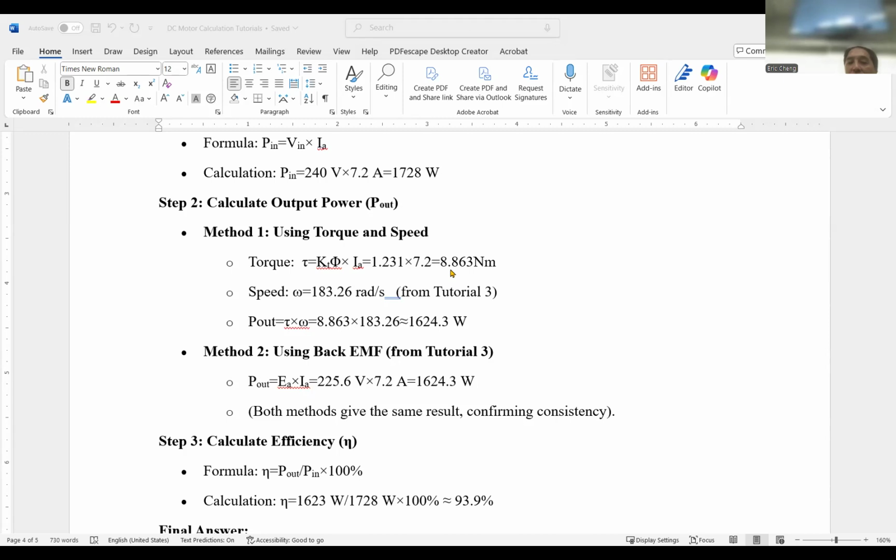If suddenly we disconnect power and connect across the braking resistor, that's what we say: we don't connect the power source, but connect a resistor to brake the motor. So this method is called dynamic braking. Calculate the initial braking current at the moment when we turn off, and also calculate the braking torque if the motor constant is 0.8. So let's see how we do that.